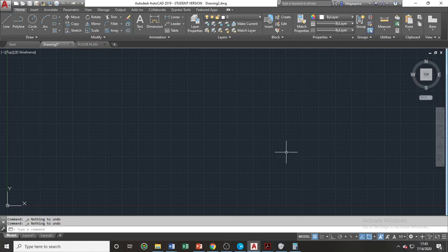We will now start working on your architectural and construction drawings with the use of the external references command, or xref command, in the attachment of your base plans. I will demonstrate first how to work on your section with the use of external references. But before you start, make sure that you adjust the units of measurement to the same units used in the drawings that you will attach in your current file.